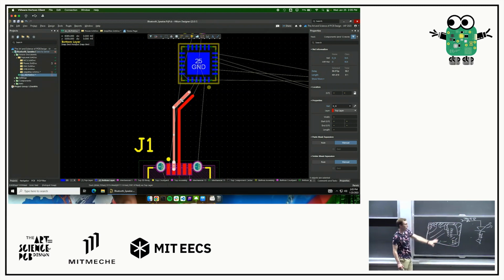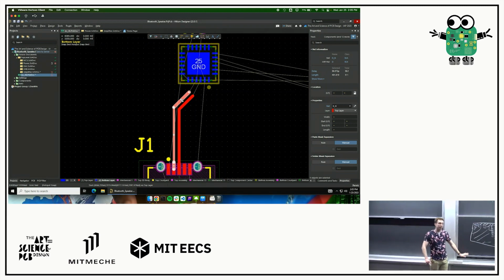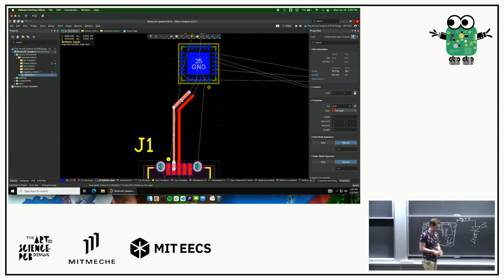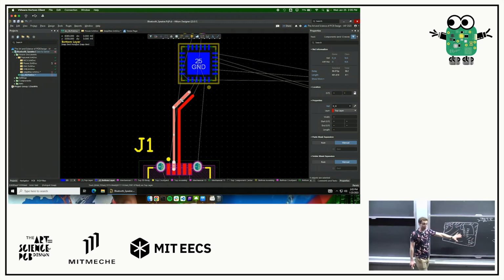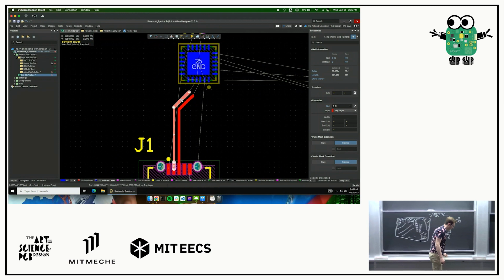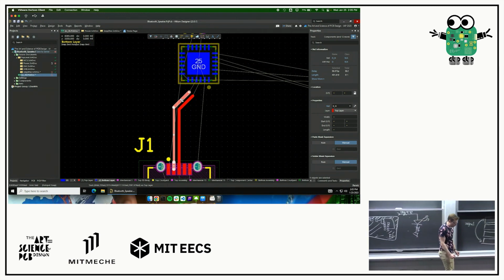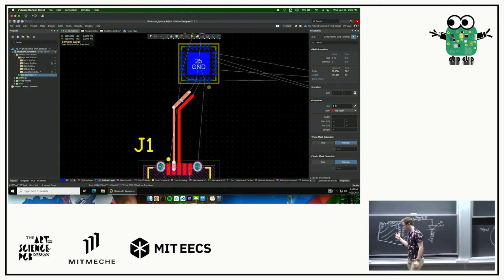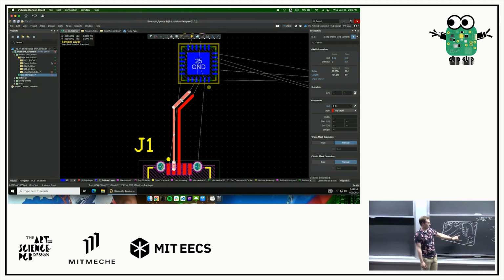And so this will cause problems, especially in digital circuits, or actually analog ones too, where having a very precise ground reference is incredibly important for your circuit to operate. So that's why we use just a massive piece of copper. It can come with some other weird constraints too, like with signal reflections and other high frequency stuff, but for most stuff that isn't weird, that's the reason.